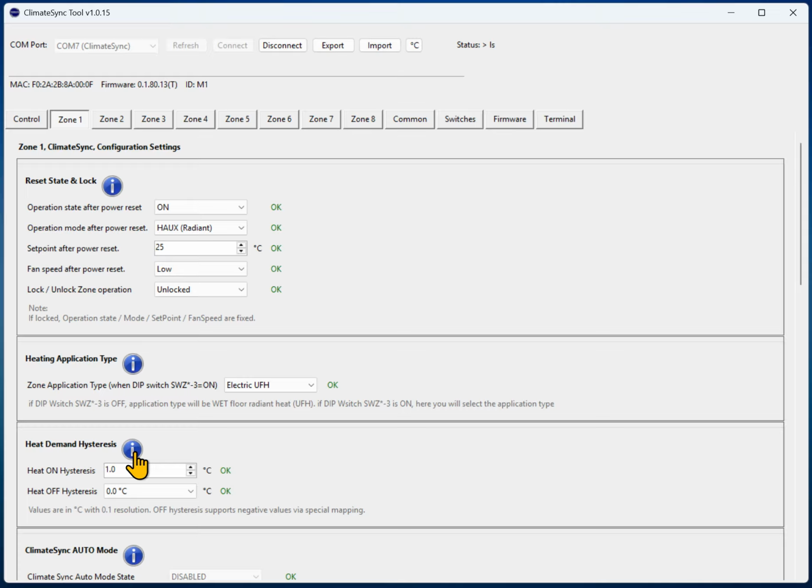If they set it to stop at temperature, for example at 23 degrees, the floor, because it's so hot, still emits heat into the room after the valve closed, and therefore it rises too high. So they want to start the heating at 21.5 degrees, stop it at 22.5 and let it naturally rise up. This way they don't get it overheated.